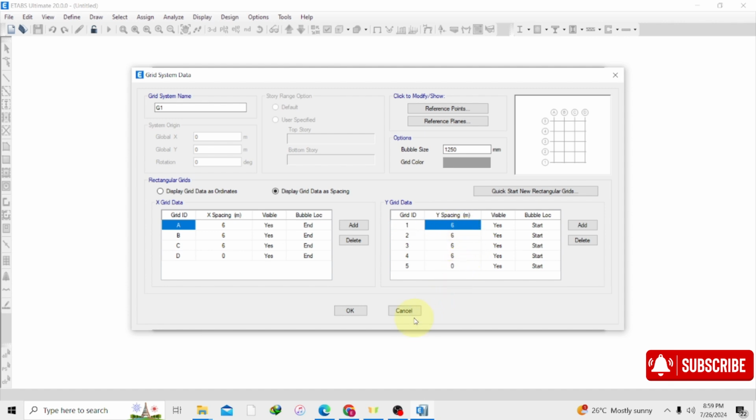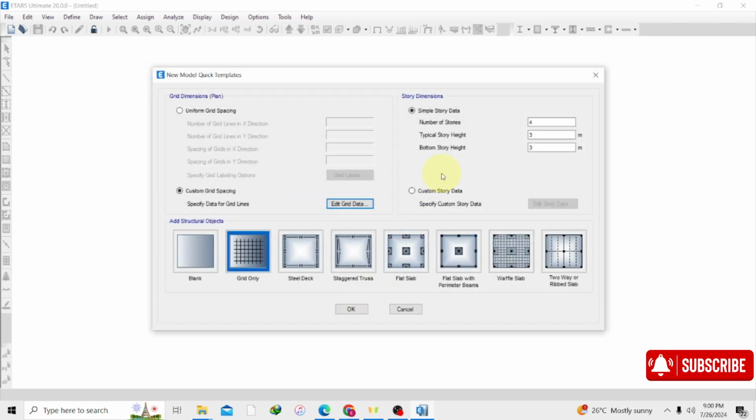We are going to change this to 4. You'll notice that the moment I tap enter on my keyboard, this spacing is going to decrease to 4 meters. Just look at that. See, this spacing has decreased to 4 meters. So now everything is intact. You just click on OK. Just looking at the bubble size, the bubble size is quite okay, so I'm just going to leave it as such. I'm not going to change anything. Then I'm just going to click on OK.